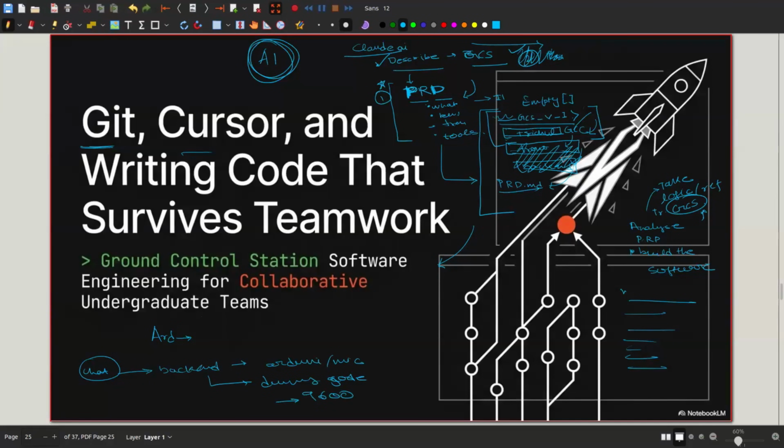Then you're going to open up the Arduino programming IDE and paste that code. You will select your Arduino and upload the code, then close this IDE and plug it back in. You will open your GCS, connect the port, and test the software.